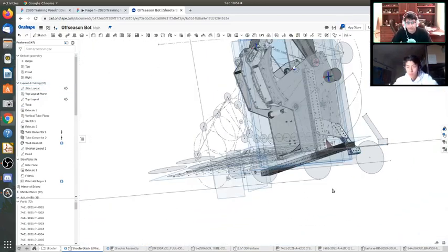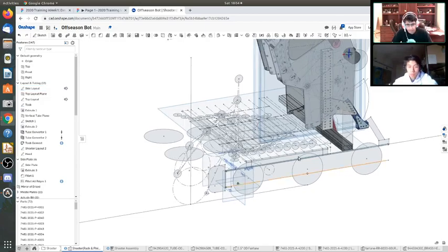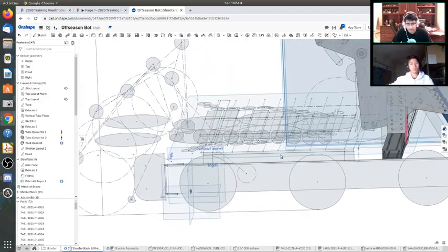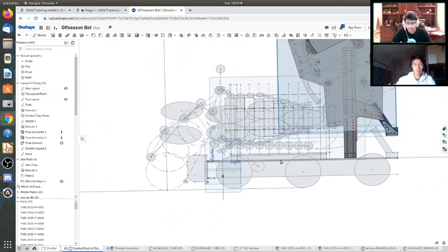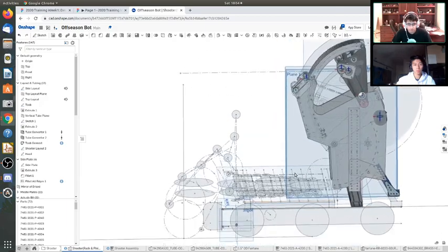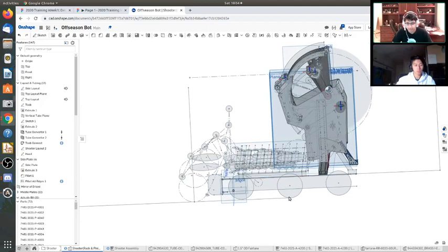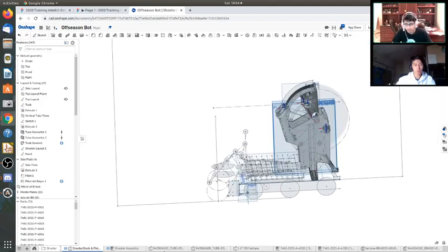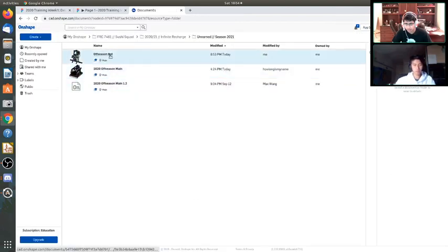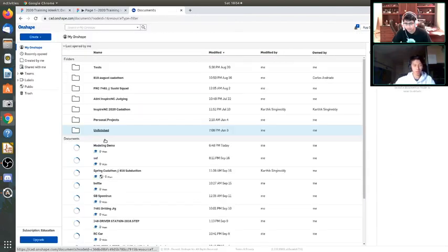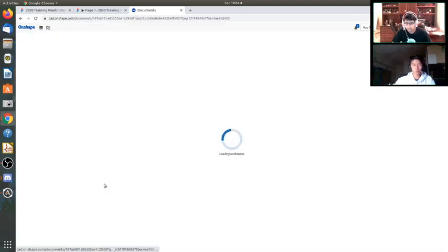Obviously there are better methods to do it, so I don't recommend doing this, because in-context part studios have a lot of issues and can break occasionally. They were the best option for a time, but we've since found better ways to do it. It's much easier to derive the part studio and then use that as the reference in another part studio.